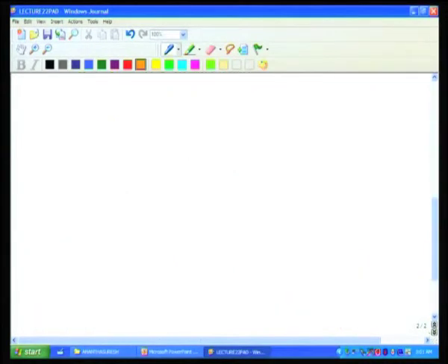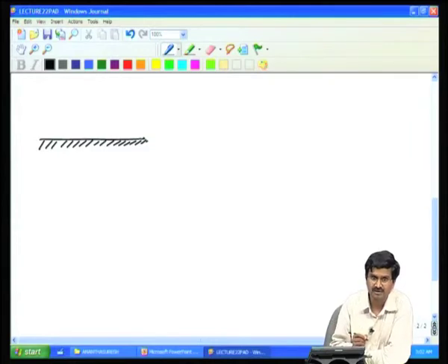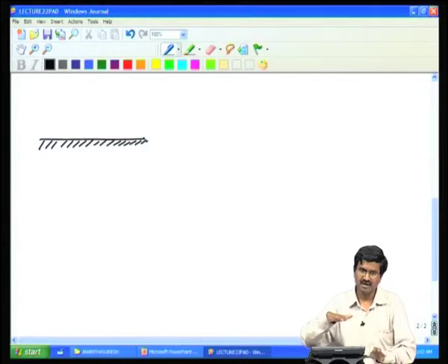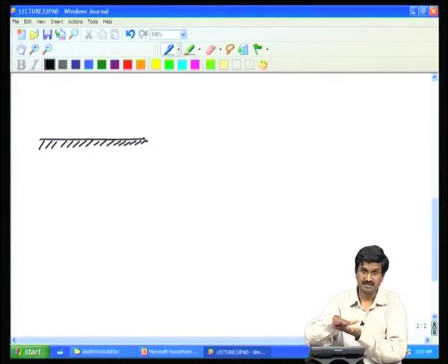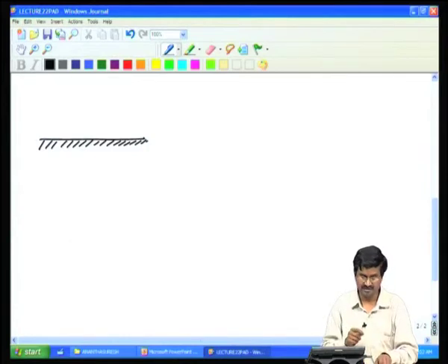So, in this flow where we have one plate fixed like this, like what happens in comb fingers, in a comb drive and other structures that are there in many accelerometers. If you take an accelerometer, there is a proof mass and the proof mass is going to move for the in plane acceleration and it experiences a fluid force because there is air underneath, air on the top, it is moving and we have to consider that force.